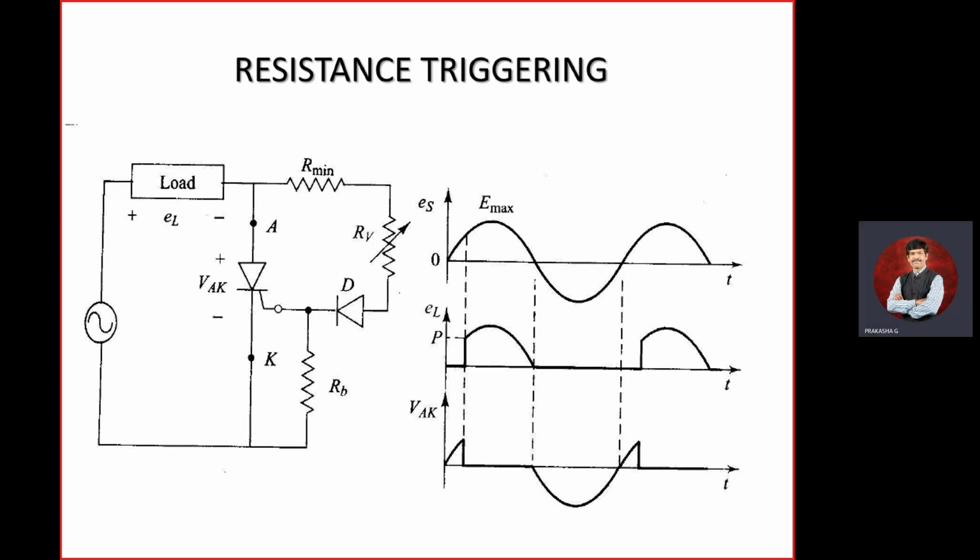Only open circuit is there. We cannot measure the voltage across the system since the circuit is not complete. The resistor is open, so it is not in a position to complete the circuit. So you are not in a position to measure the voltage drop across the load. So voltage drop is 0.